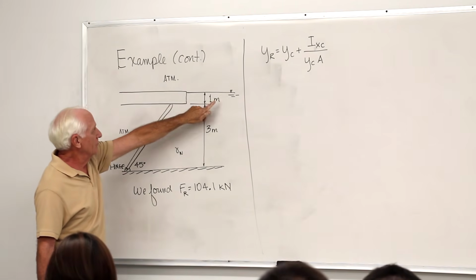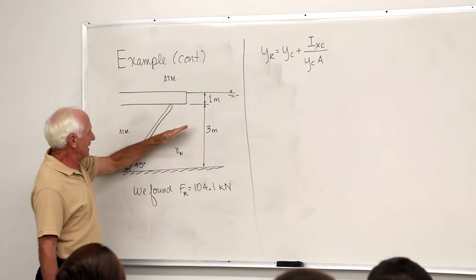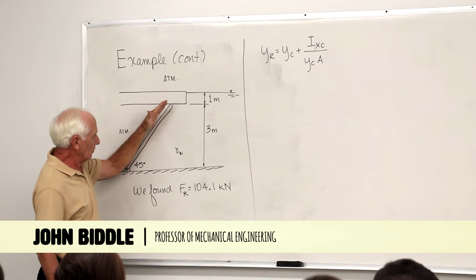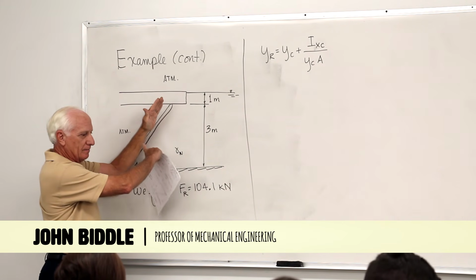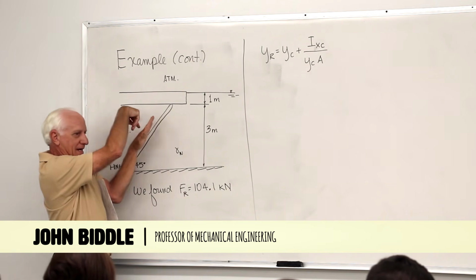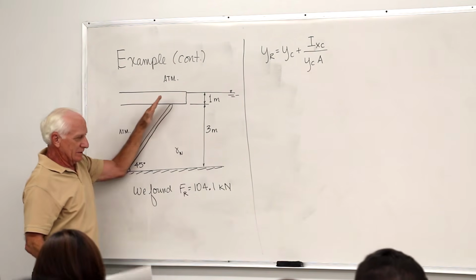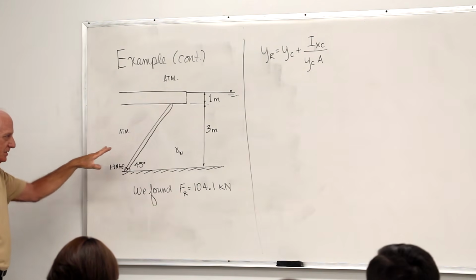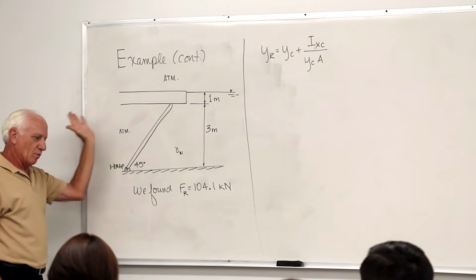Air up here. Free surface. The gate popped up here. Water pressure acting on the bottom, pushing it this way. Weight of the gate acting at the centroid wants to pull it down this way. We were supposed to see if the gate was in equilibrium at that position or would it drop.